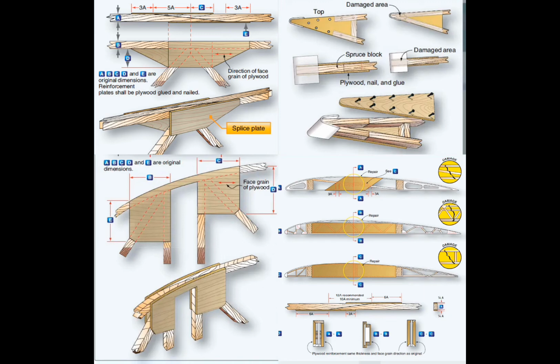How can the moisture content of wood be determined? Moisture meter, or you could take a sample, weigh it, put it in an oven, weigh it again after baking, and do some math formula. What area of the wood spar may not be spliced? Underwing attachments, landing gear fittings, engine mount fittings, lift and interplane strut fittings.